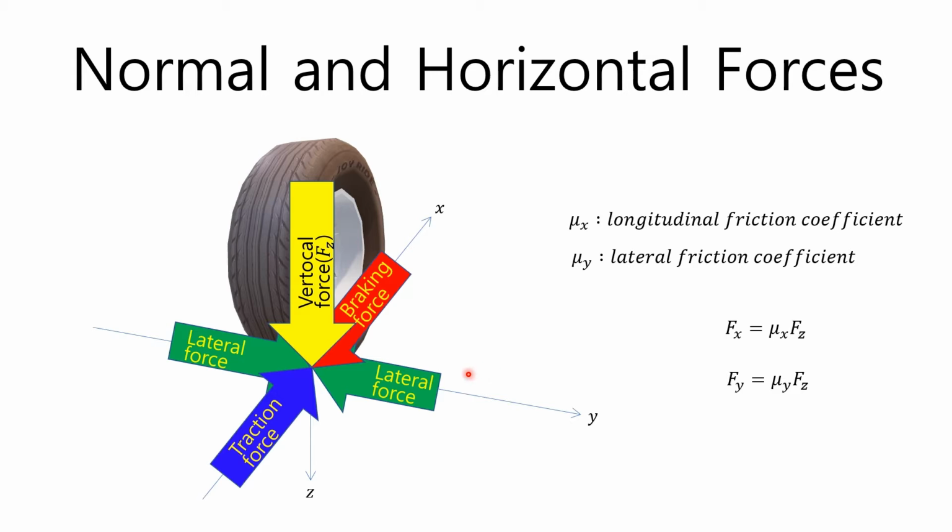The vertical force does not necessarily have to be large, but the vertical force change can be used to perform high-performance driving. For example, if the vertical force of the rear wheel decreases due to braking, the friction of the rear wheel decreases and the steering wheel can be rapidly rotated to slide the rear wheel, and the developed oversteer can be used to make a sharp turn or a 180-degree J-turn.